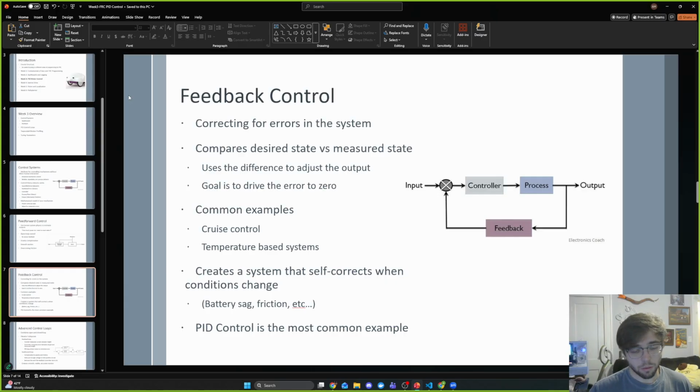Like I said, the biggest one is encoders, which are essentially sensors that you mount on a motor shaft or something that spins, which translates to motion. You can measure the rotations of that shaft or axle and figure out distance based off of that. This is great for feedback control, especially, we'll go back to the elevator system, where you can convert those motor rotations into elevator height.